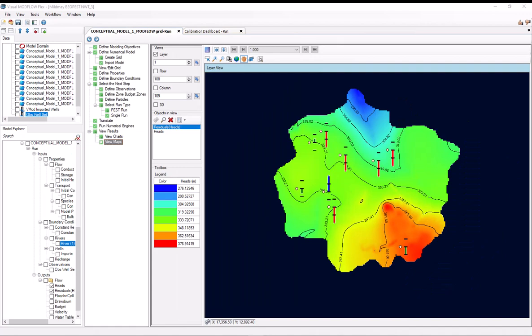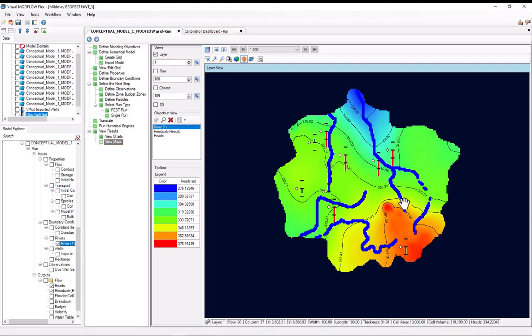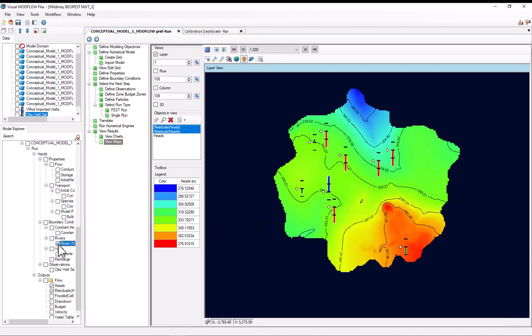So I've taken some time to improve the calibration of the model, and as you can see, in this calibration, the output heads are much more realistic. We don't have the gigantic head bullseye anymore. The reason why the previous model was so out of whack had partially to do with the fact that there was a pilot point in a river boundary condition, which I moved over. In general, your pilot points should never be in the same model cell as a boundary condition, as this will lead to poor results. Another thing that I changed for this PEST calibration was I changed the flow engine to